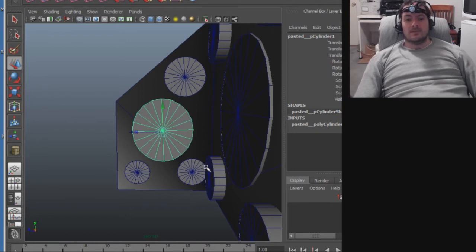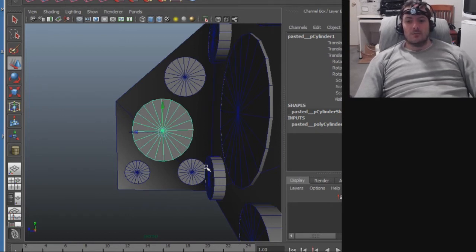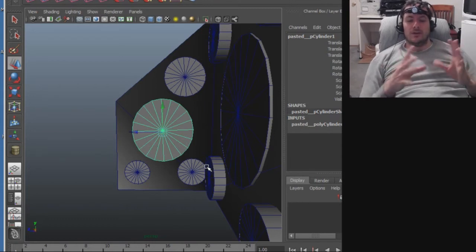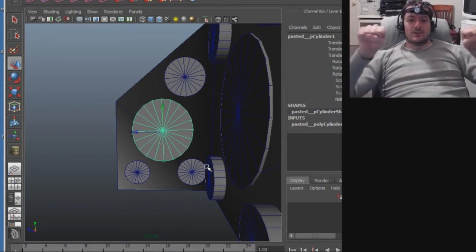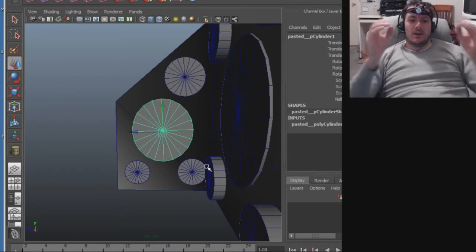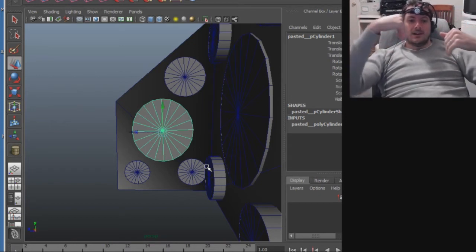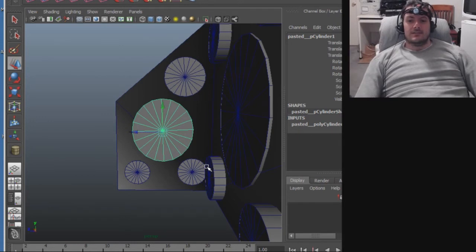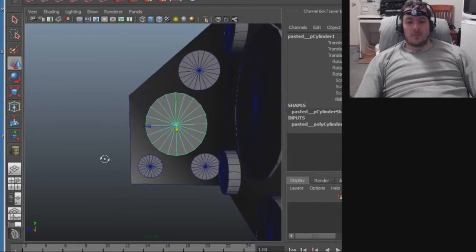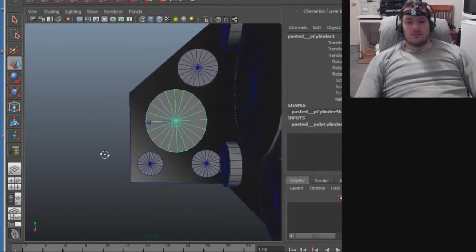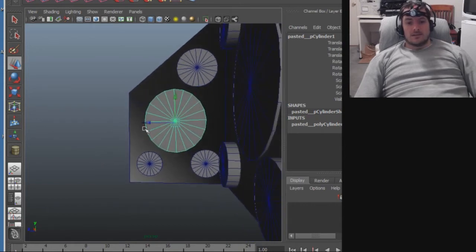The problem happens when higher layers want to rip up lower layers and make them curve upward, like a bow and arrow bow. If you're taking the string and trying to shorten it, it bows it more. Well, we're just cutting that string into segments so it can't have that powerful force. The longer the string is, the more it will try to warp it, the more it will bow the lower layers. So we're cutting the strings up into segments.